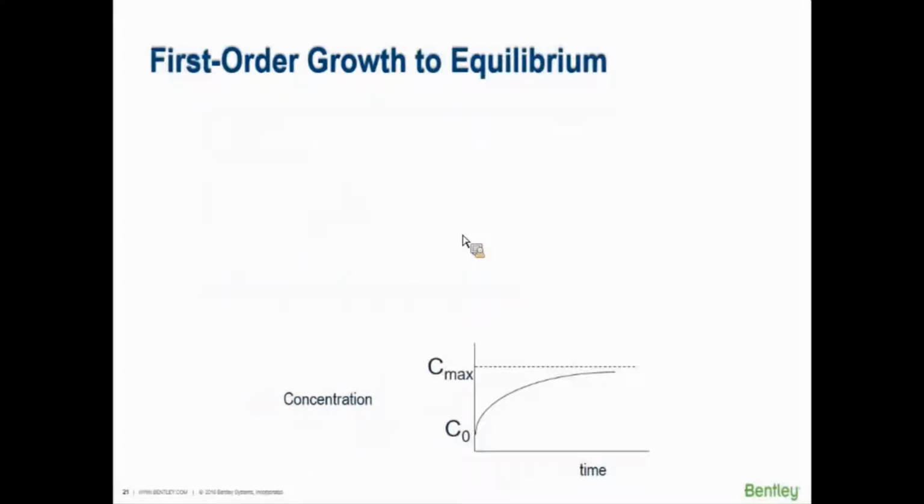And then on the other end, first-order growth, instead of zero-order growth, is not linear; it's something that exponentially grows over time. What's potentially growing over time, and then reaches some concentration max? DBPs, disinfection byproducts, also called harmful disinfection byproducts. That would be haloacetic acids, HAAs, and trihalomethanes, THMs, things that we don't like to have forming in the system because they're carcinogens.